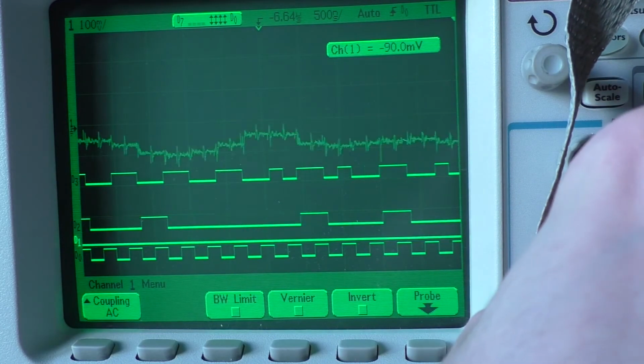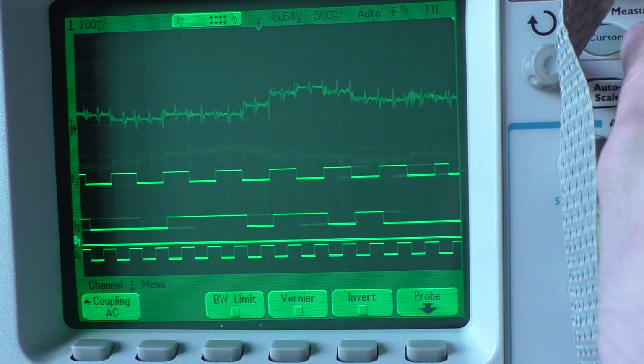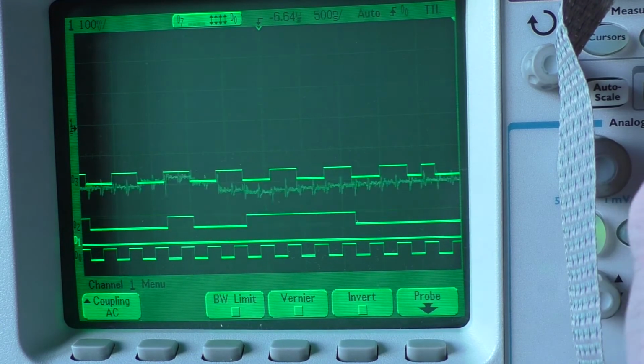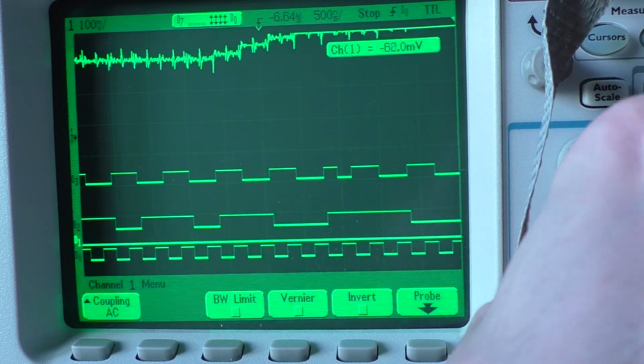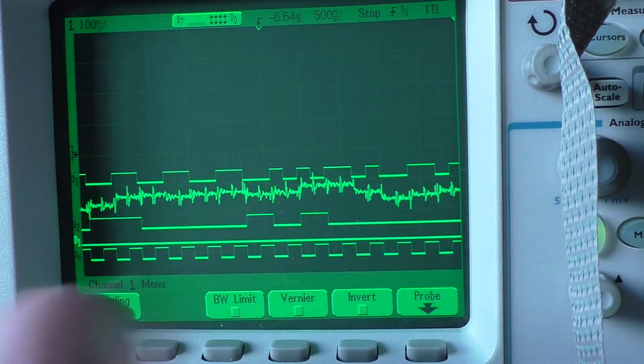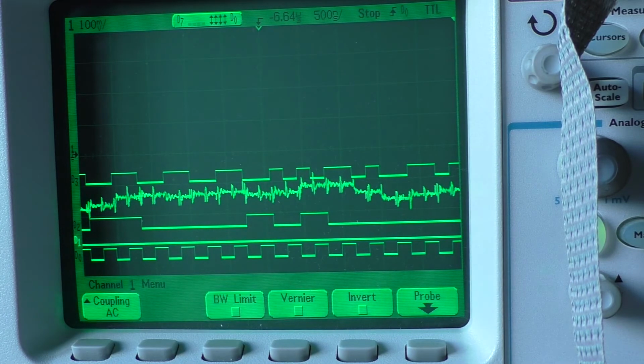So you can see how the DAC actually forms the signal, but this doesn't mean that the actual headphones output is staircase shaped, because it has to be run through a low-pass anti-aliasing filter as part of the digital to analog conversion.